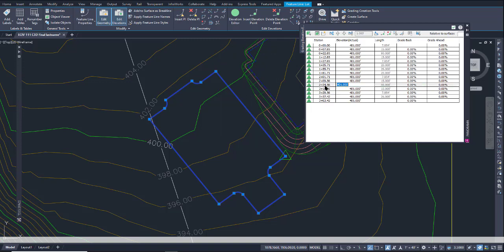Okay, that's this elevation here, this triangle here. So I'm going to go from 401, and I'm going to change this elevation at 2 plus 24.56 to 396. Okay. All right. So then that gives me my fall all the way down of 5 feet. So that's a nice way of letting my water flow.